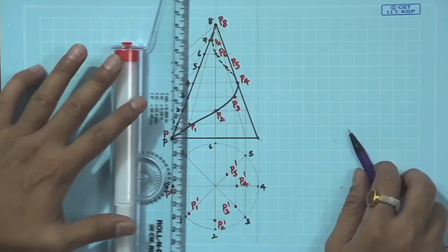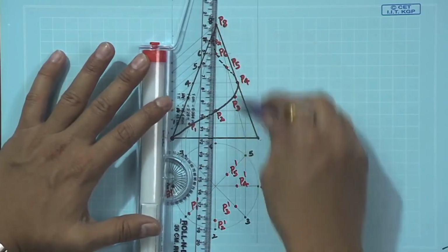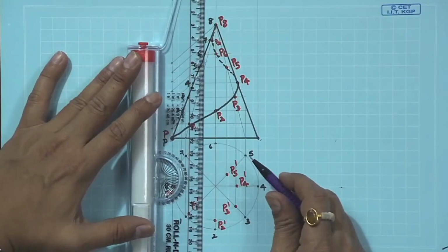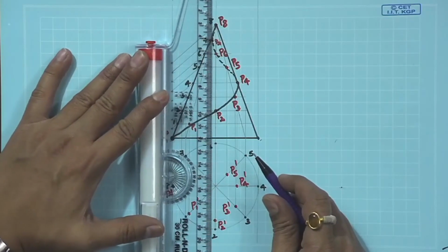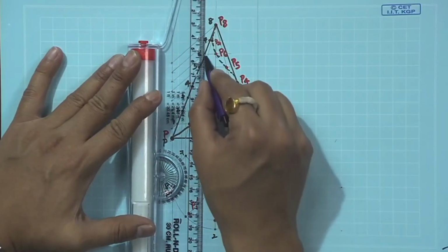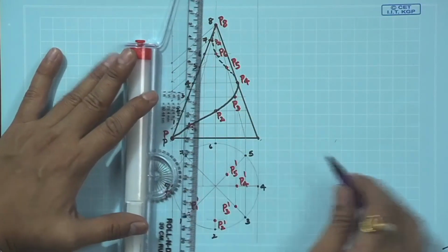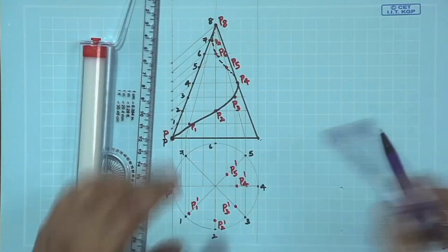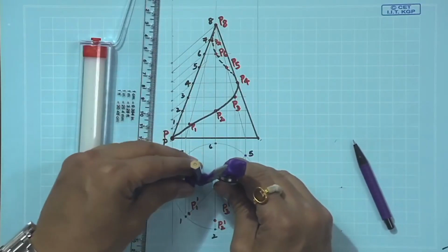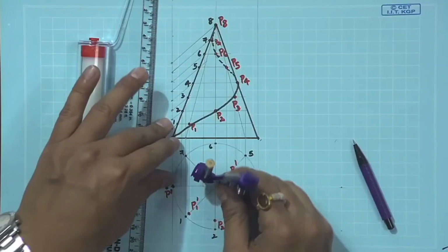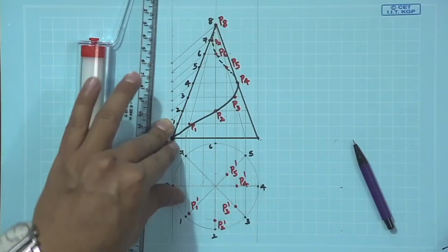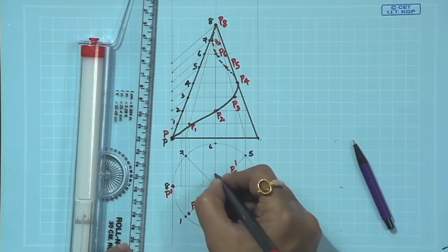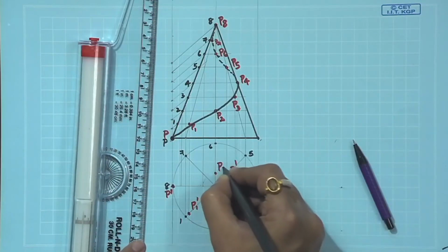For 6 again, it goes via this point. However, we want precise measurement, which is going parallel to this 6. So, we intersect the horizontal one, measure the distance of this point on that axis. It makes here, connect this point as P6 prime.